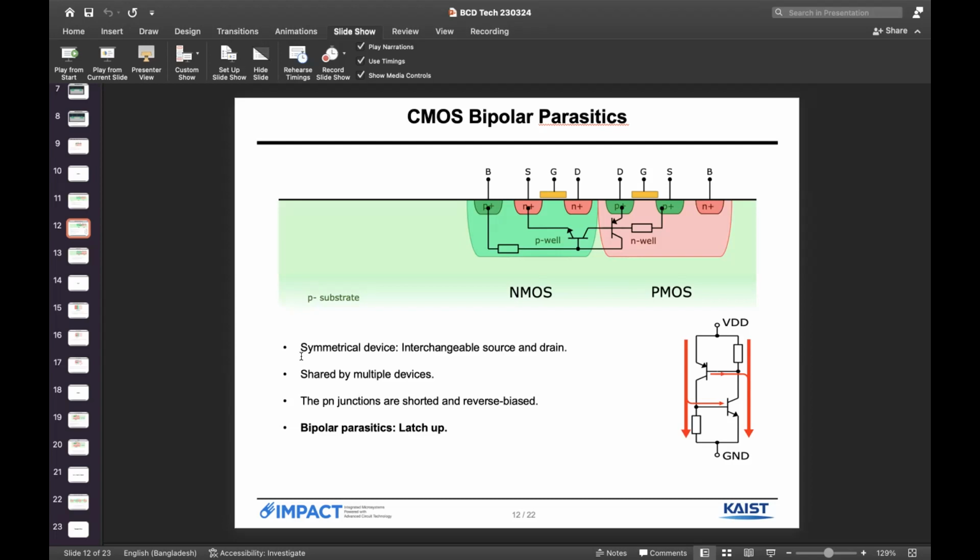So it's because also there's a resistor at your drain here, so that may make the gate of the BJT fluctuate a little bit. So it's not happen frequently, but in some case they did happen. So they will actually turn on the two PMOS accidentally, and then they will conduct a really high current flowing from the VDD to ground, but that happened for only really short time. But even for a short time, if we have a really high current flowing through it, that might be a problem. Short circuit, right? Yeah. So actually, it's short circuit from VDD to ground.